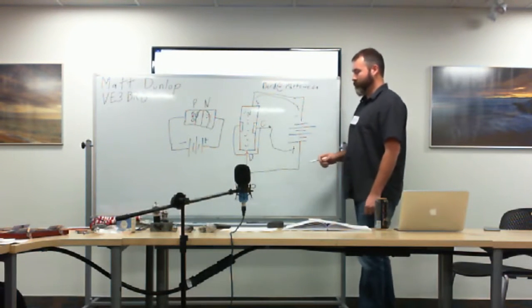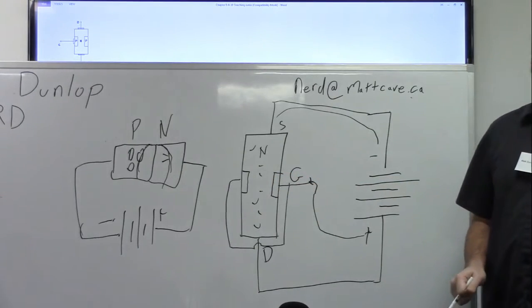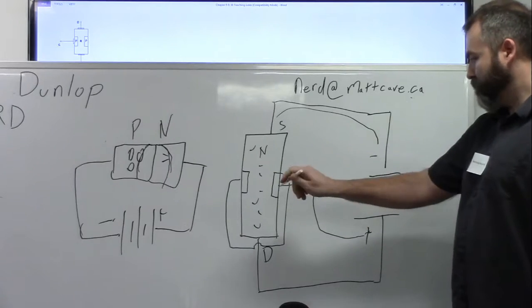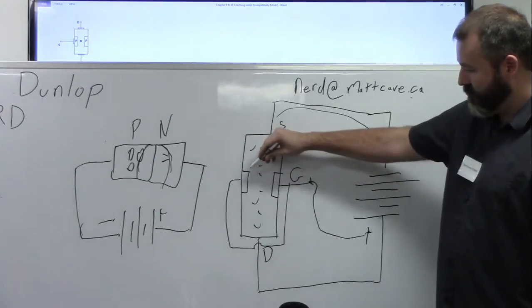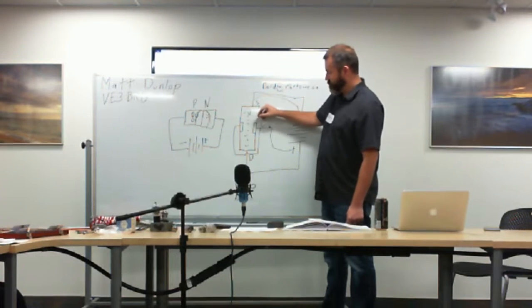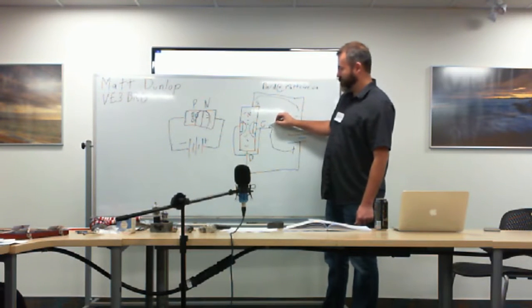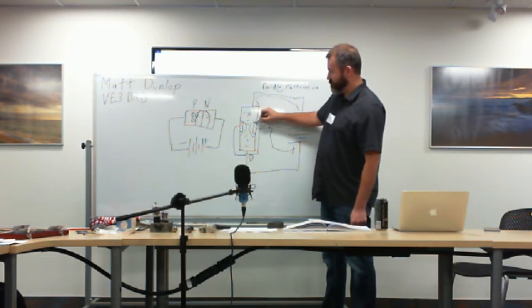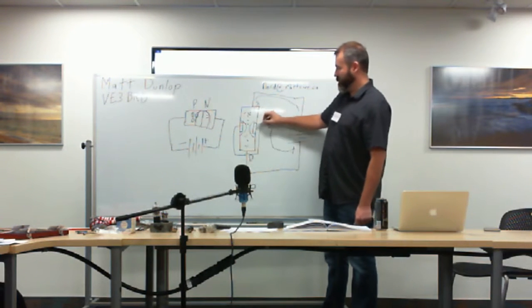So in this case, what we're going to do is reverse bias this. When we reverse bias this, it causes the depletion zone to form across the gate. So it starts forming across, and the more electricity we apply to this, the more the depletion zone grows. So you see it's creating a pinch point in the flow of electrons through here.